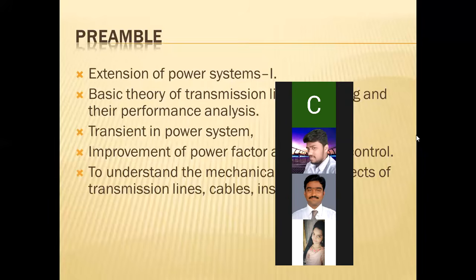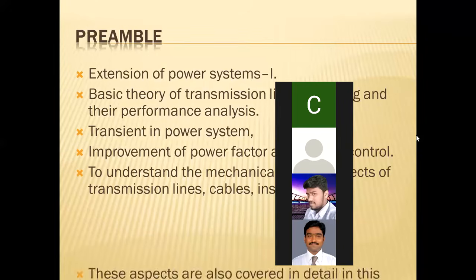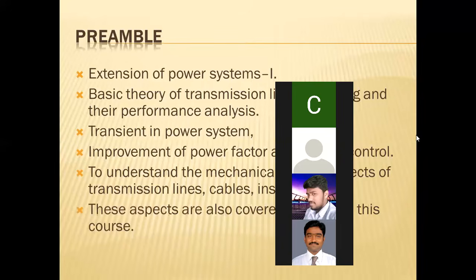A cable will have a number of leads for several phases of supply. And the cables will need adequate insulation for earthing as well as interconductor insulation. And as the cables are run under the ground, the required mechanical strength, insulation, moisture protection, etc. are to be considered. All these things will also be learned in the course of power systems.